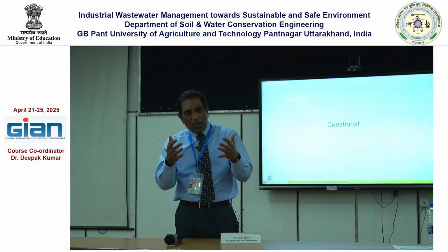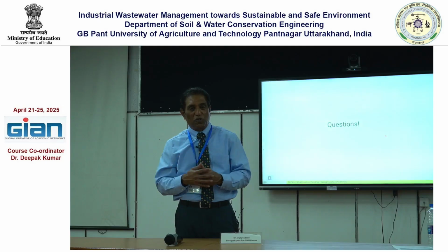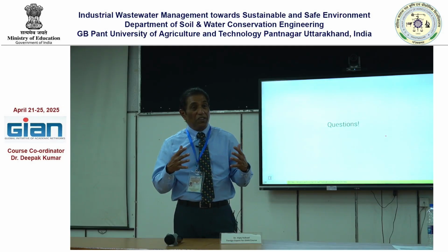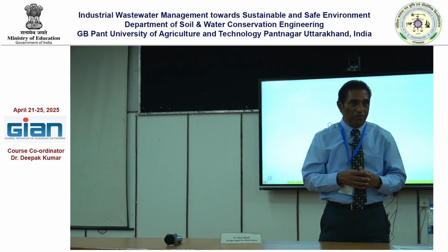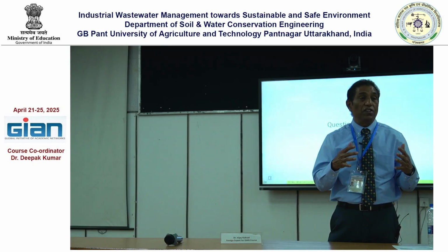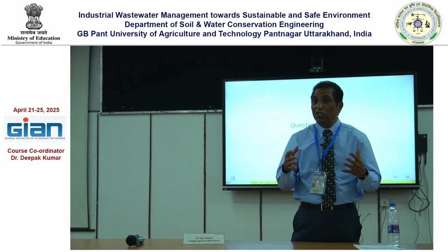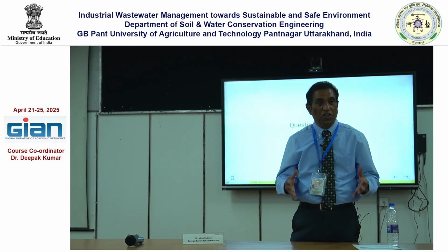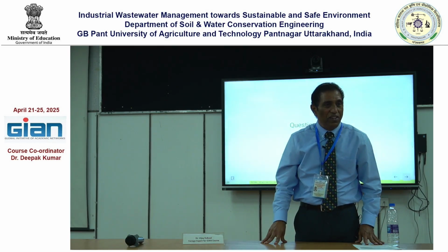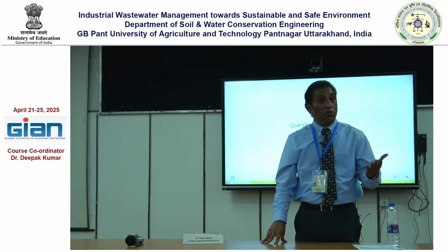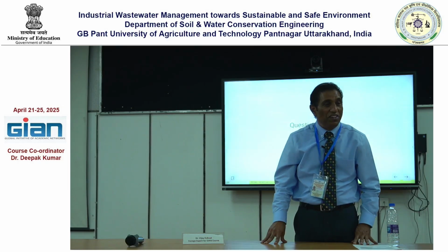But biosolid is also a component of the treatment plant, right? You should have regulations for that also. A big treatment plant can make good economic decisions on that. They can use this for manure production. That is why it has to be checked for contamination. If it is contaminated, what will you do? You need a space to dispose of it. You cannot just go and dump anywhere, even for road construction or anything, because you know it is contaminated. Because you have measured. If you have not measured, you can do anything, right?